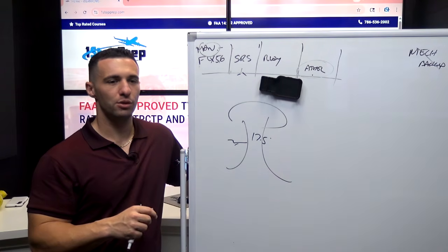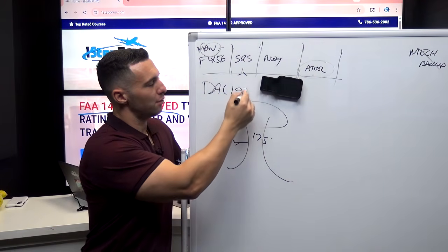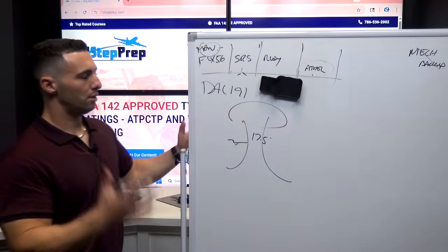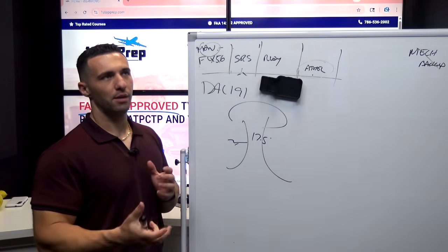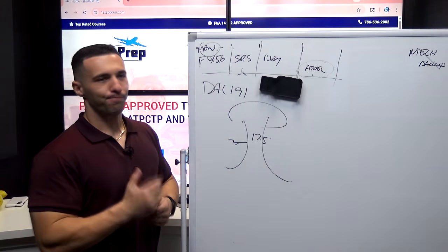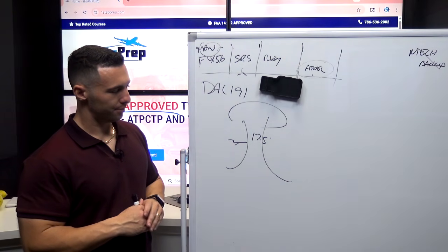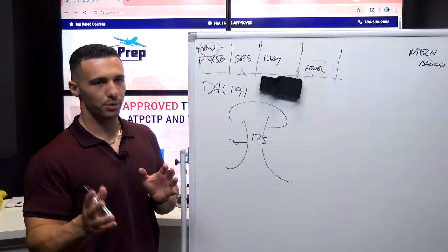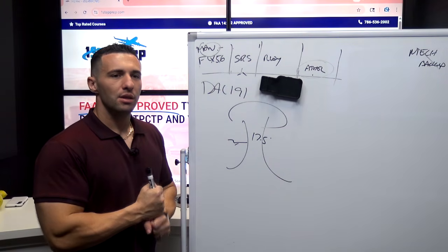There's a really good video on YouTube. It's Delta 191. This was an L-1011 going into Dallas that crashed due to wind shear, unfortunately. When you listen to the cockpit recorder and you also see some of the inputs that were applied, there was some mention of airspeed. There was some nose-down pitch control inputs. Anyway, I won't get into the detail of it, but suffice it to say that the procedure talks about RA, and it does not mention anything to do with airspeed, everything to do with vertical trend. Okay, let's see.